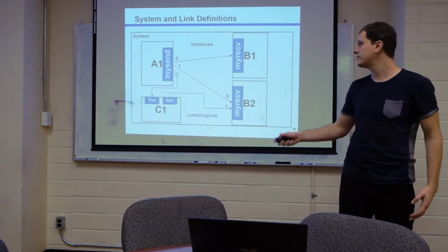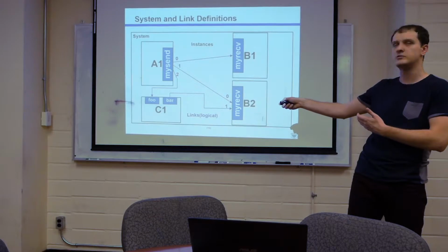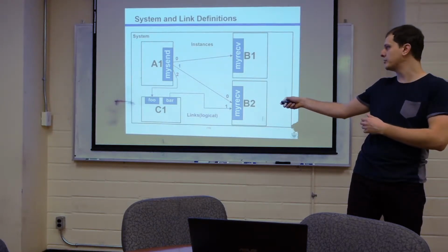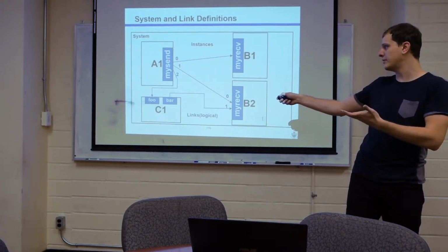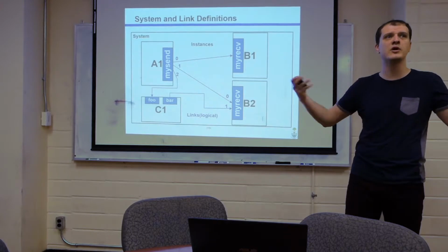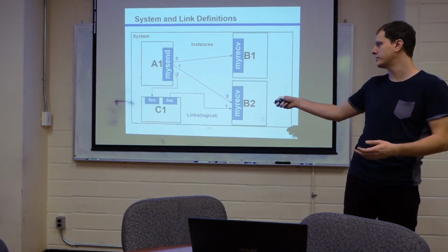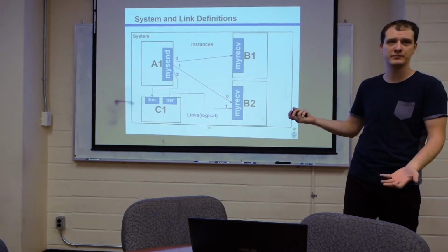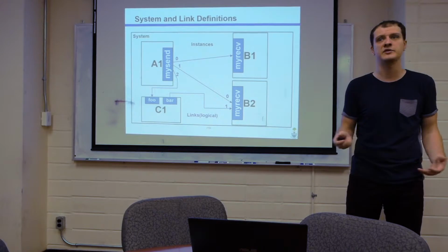How multicast is achieved is actually pretty simple. Instead of having 0, 1, and 2, imagine these were all 0, 0, 0. That's allowed, because those zeros belong to the link, and all these 3 links can have a 0 source address. If that were true, then when my send interface here drives a 0, it will simply broadcast it to all 3 of them. And you can have some combinations like 0, 0, some other number, and multicast to the sum of them. So via this addressing scheme, I can implement multicast and broadcast as well as unicast transmissions.